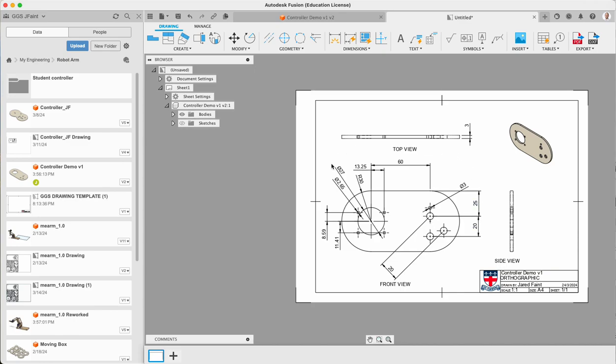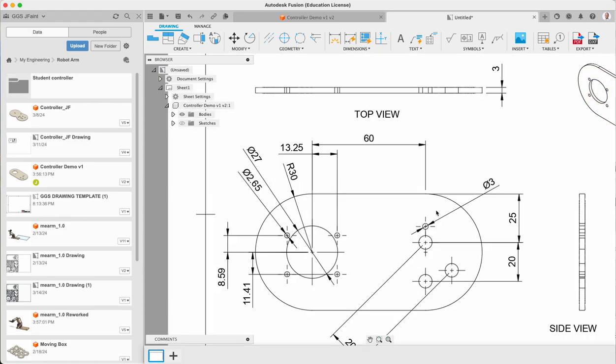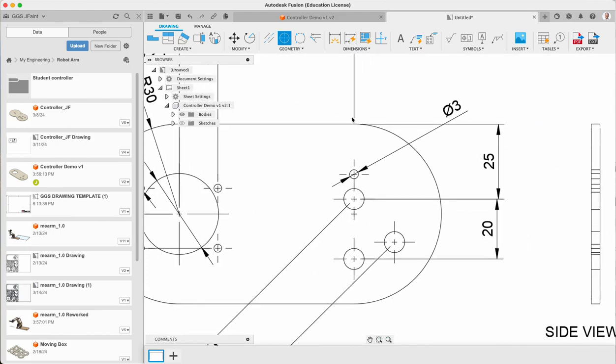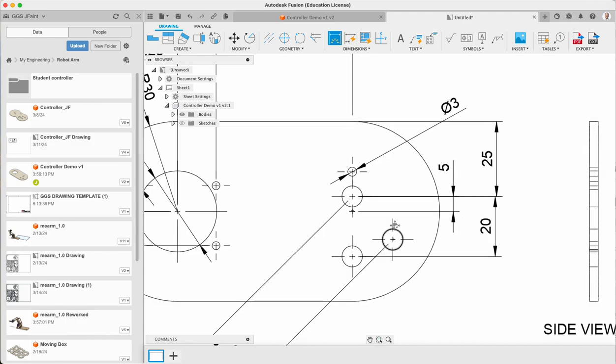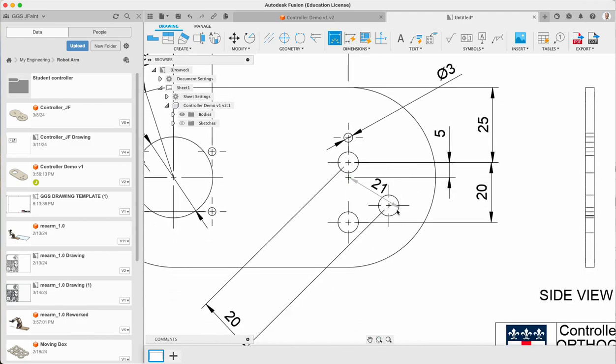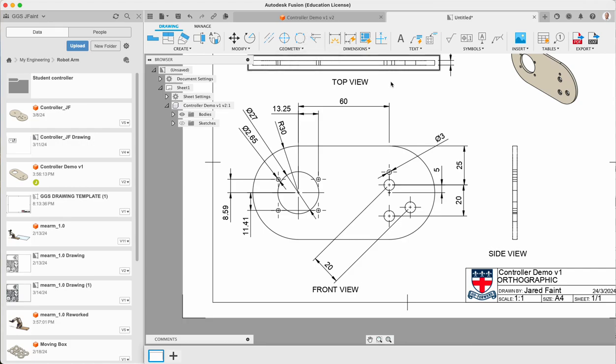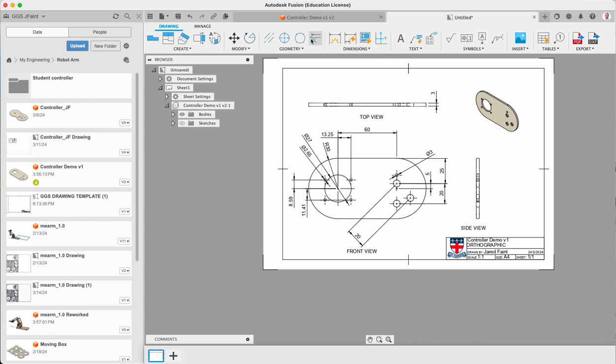And you need to do the same for yours. So thinking about all the measurements you've added in to be able to recreate your design. Once you finish that, you've got your dimensions, you've got your center lines for any circles or arcs. So you can see on this side, if I go to that center line there, we've got our nice little mark in the middle. So if I needed to, I could actually do some measurements from that point as well. So if I wanted to work out how far it is from the center mark to there, I've got those dimensions as well. So it starts getting a little bit busy at times, but if you need, we've got some nice little ability to make items sorted out like that.